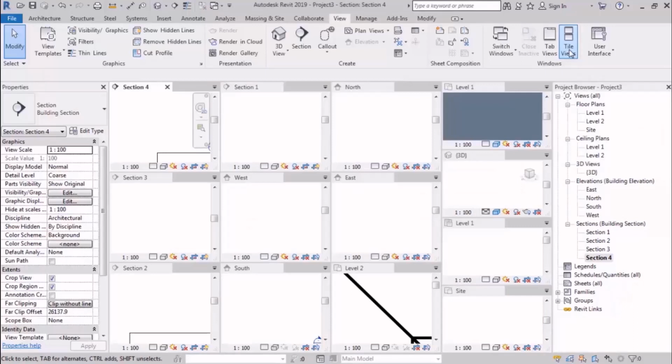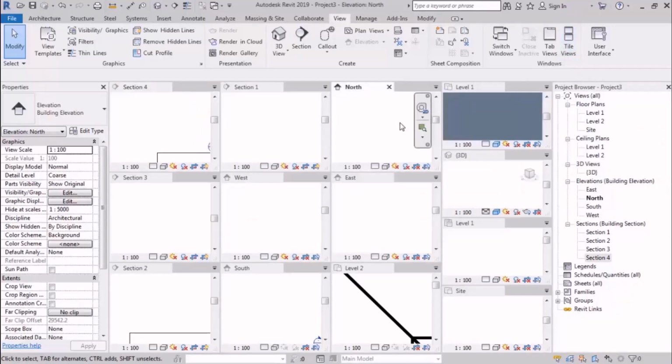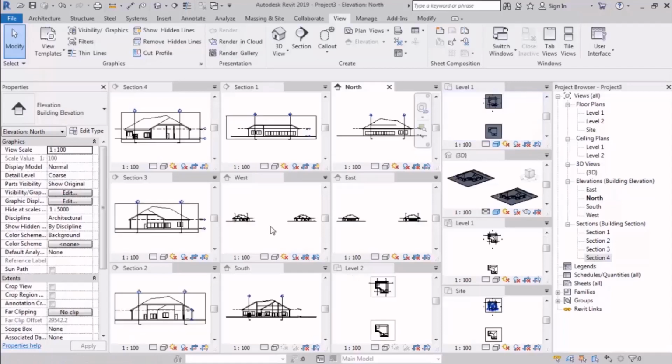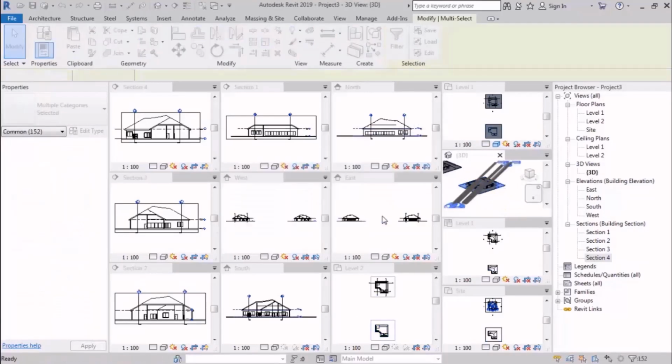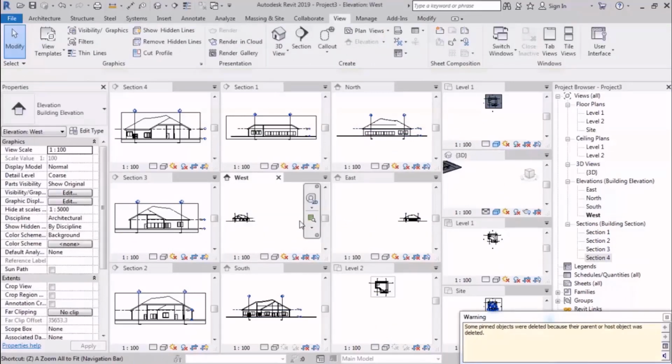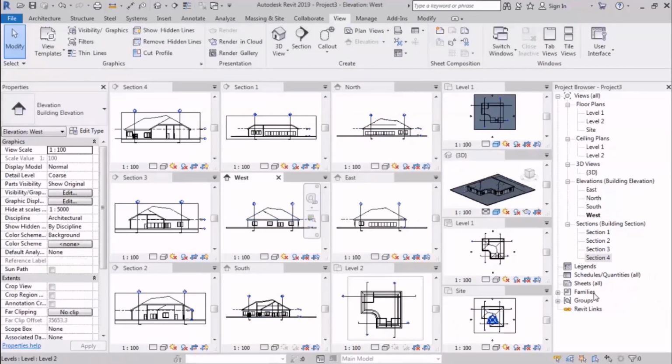But now we can't see our project between these. And we actually need something like the zoom extend in AutoCAD, which fits the project in view. In Revit, the shortcut of the zoom extend is ZA. If you press ZA, you can see that's how it will be. For example, I will delete one of these, and again I will press ZA. As you can see, our project will fit in our view.